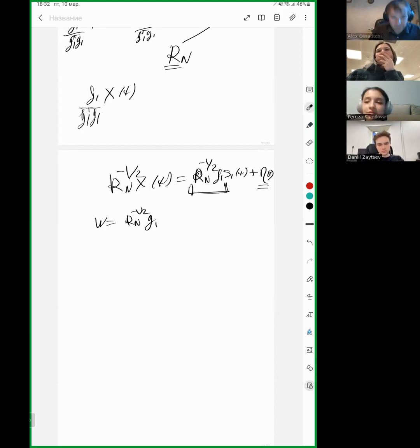It will extract something from the data. Therefore, it will be spending its degrees of freedom not to cancel all possible sources, but to cancel only those sources that are present in your data. And that's why you get the so-called super resolution properties of the beamformer if you use it in the scanning mode. I will show you what it is.